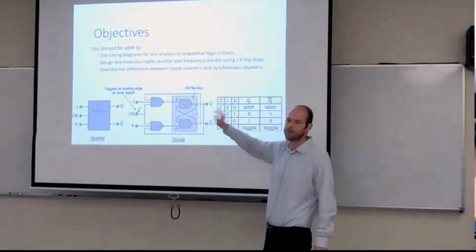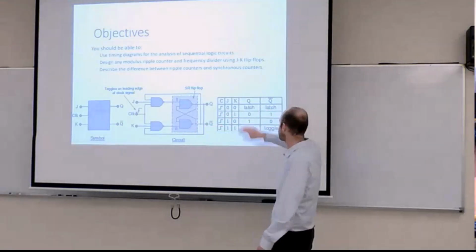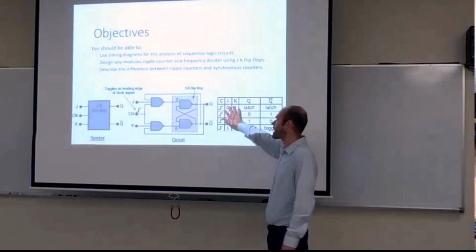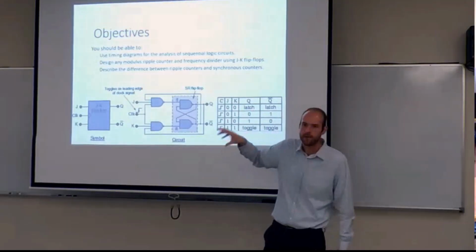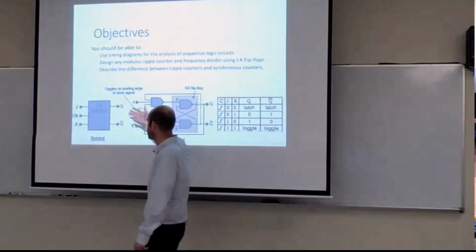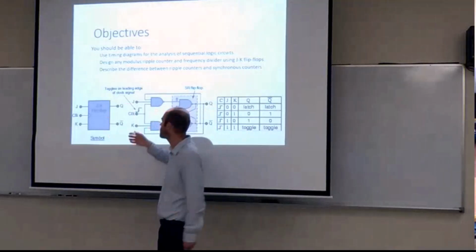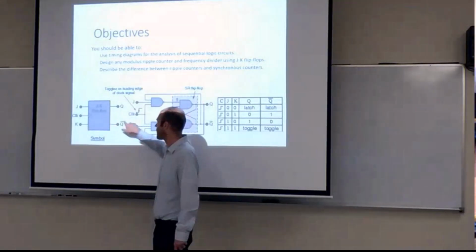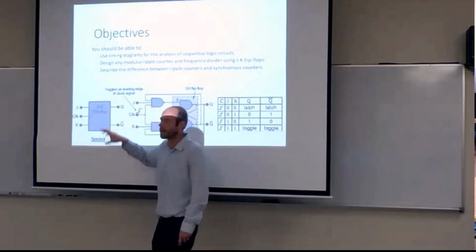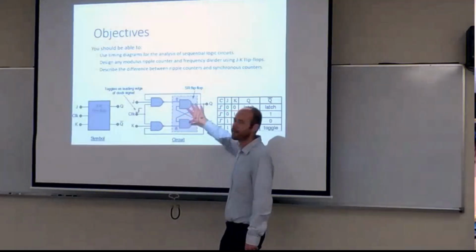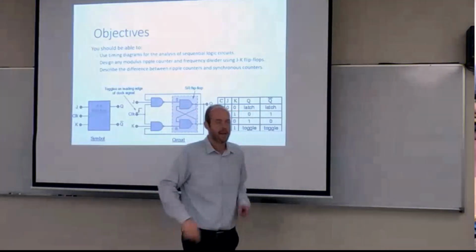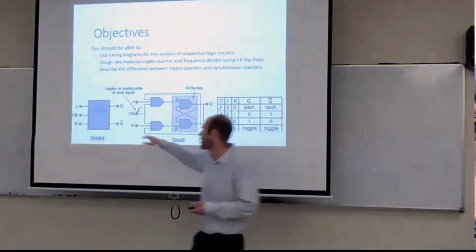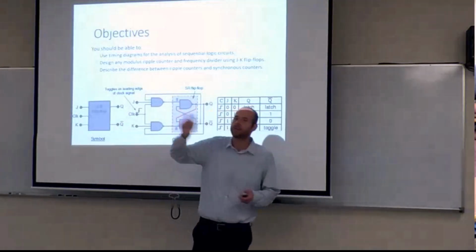So finally, those are some details of the JK flip-flop. And remember that when J and K are 0, it just retains its previous state of Q. And that's called a latch condition. Note that the JK flip-flop has a Q naught that just comes out based on the internal setup. Sometimes we use Q naught. We'll look at some use cases later, but Q naught, or the bar over it, as we know from our algebra, is just the inverse of Q.